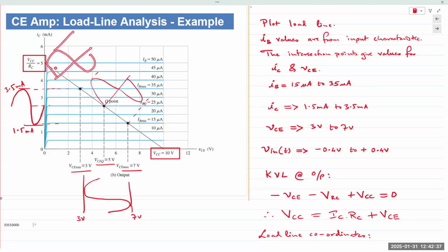So the top half of the waveform is now clipped off. You've driven the transistor into saturation on the left. Remember, this is the saturation region. So if your input is right there, your output would be somewhere here, something like this. But the transistor cannot give more than this waveform.